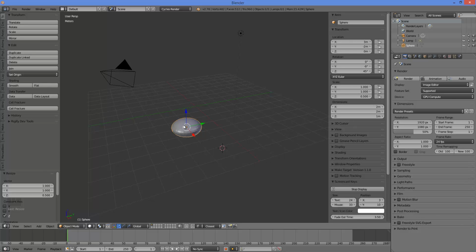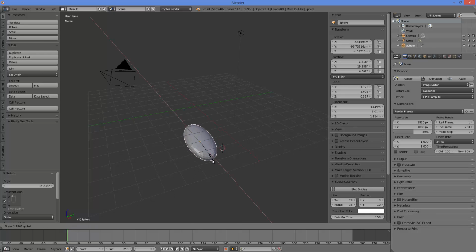Another way to move, rotate and scale an object is to use the gizmo, a small set of 3 Cartesian axes positioned on the object origin. Just click and drag on one of the axes. The object will move in that direction, while clicking and dragging on the small circle on the center, you will move it freely in the space. You can do the same for the gizmo rotation, here. And for the scale, by clicking here.